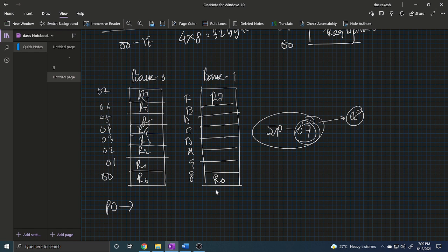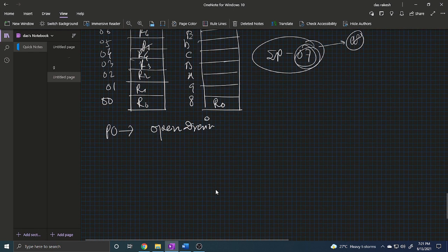So now this P0 is pulled up by the resistance, otherwise there will be no current flowing to the port. That's why only port 0 has an open drain connection. Please note that only this is an open drain connection. So that's why the 10 kilo ohm resistance connection is necessary to transfer the data or to take the data from port 0.